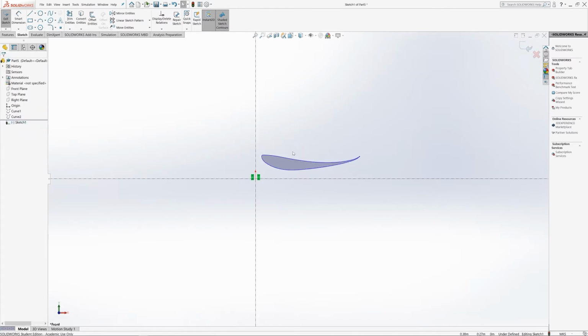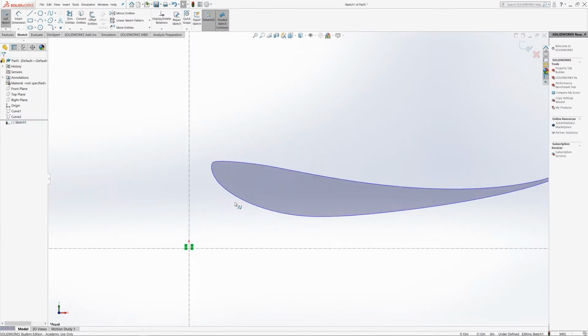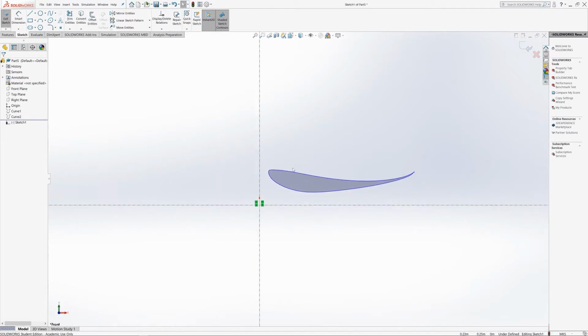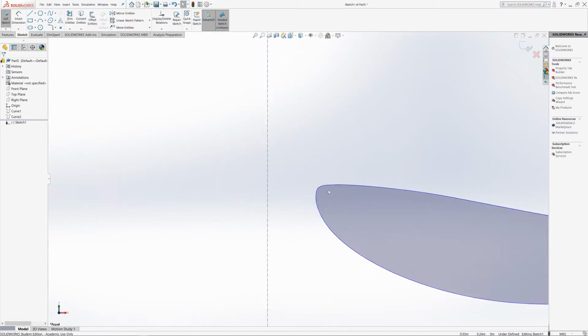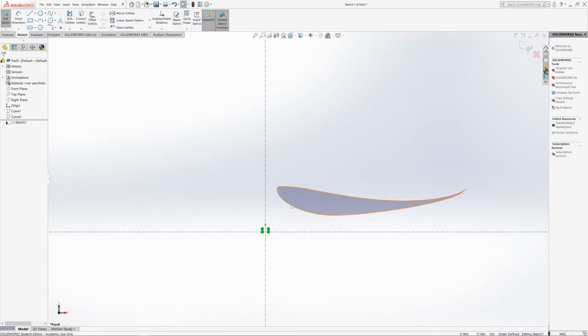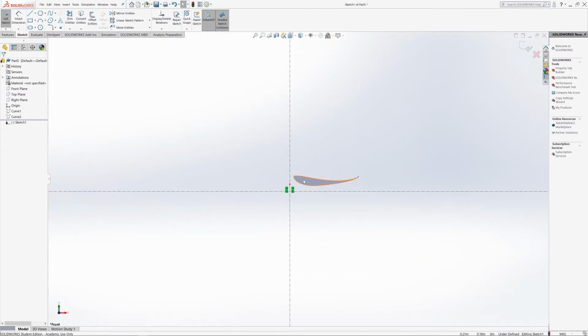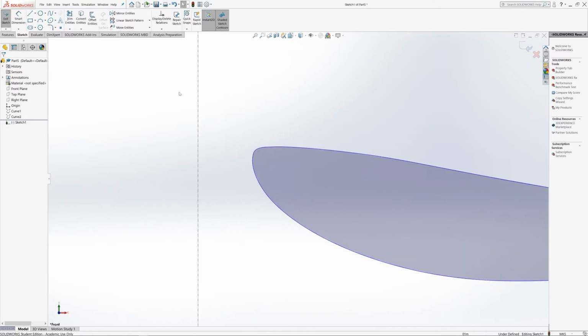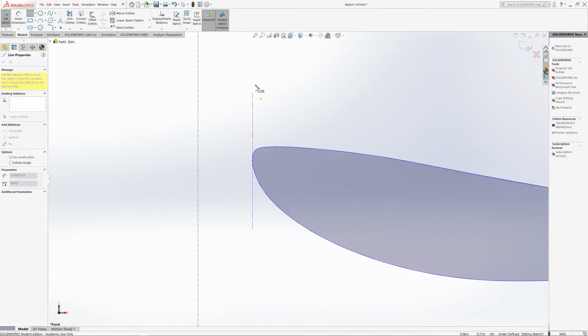Okay, so the first thing that I'm going to do before I do anything is draw some tangents on the airfoil. These tangents would allow me to position the airfoil more accurately or precisely, and they'll also help us define the slot gap geometries later on for the subsequent flaps. So the first thing I'm going to do is head over to line, make sure it's a midpoint line and it's for construction. Vertical. So this vertical tangent here is going to mark out the foremost point on the airfoil.